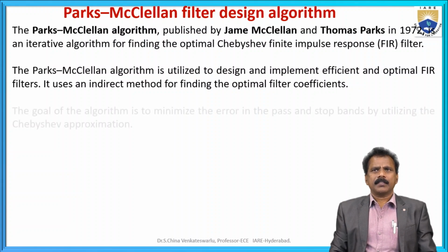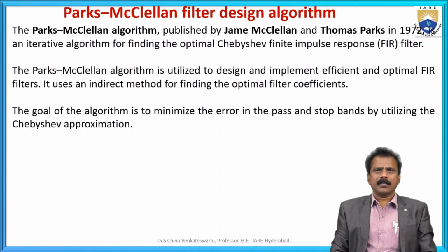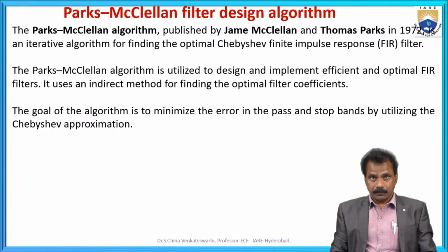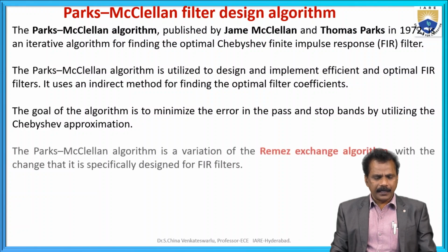The goal of the algorithm is to minimize the error in the pass band and stop bands by utilizing the Chebyshev approximation. This is the popular windowing technique, where it is Chebyshev approximation. The Parks-McClellan algorithm is a variation of the Remez exchange algorithm.